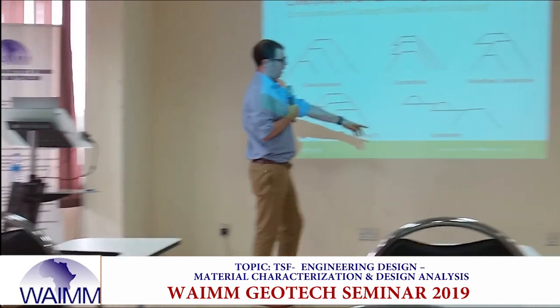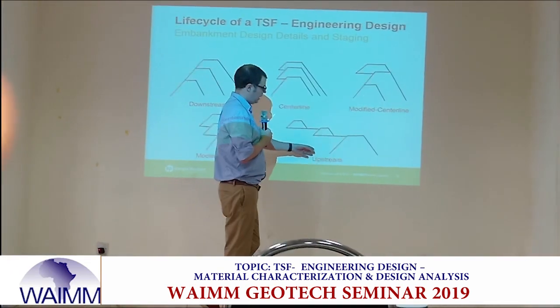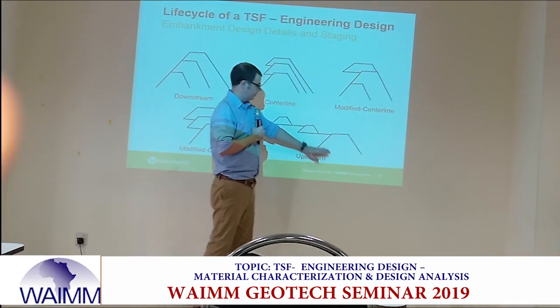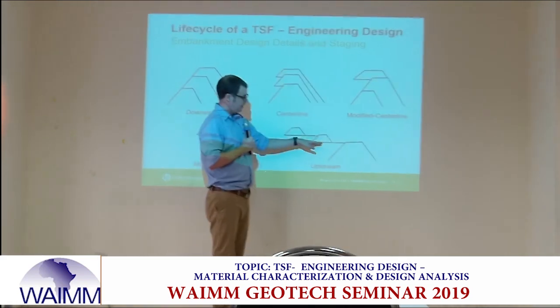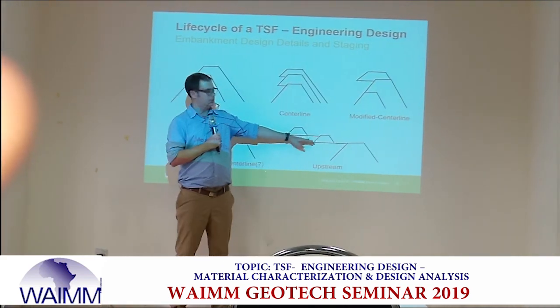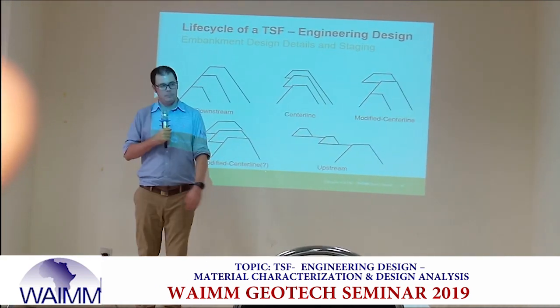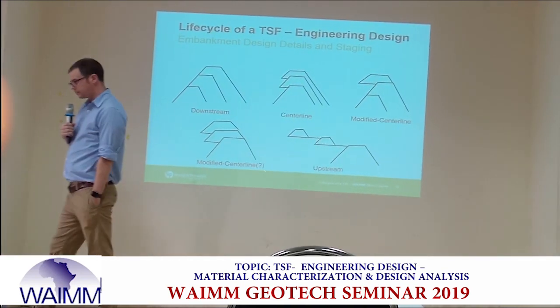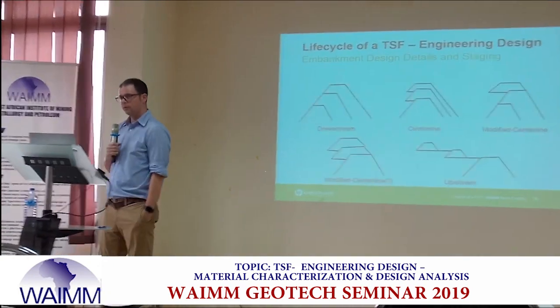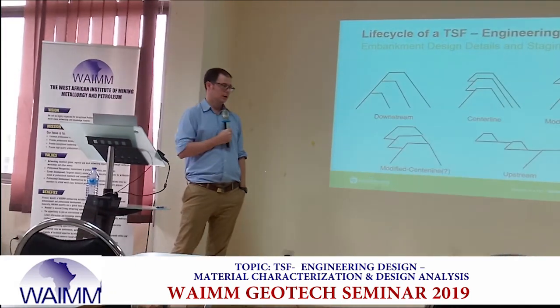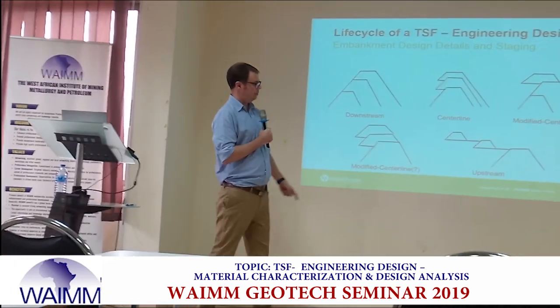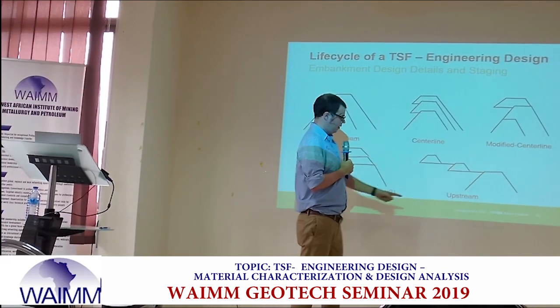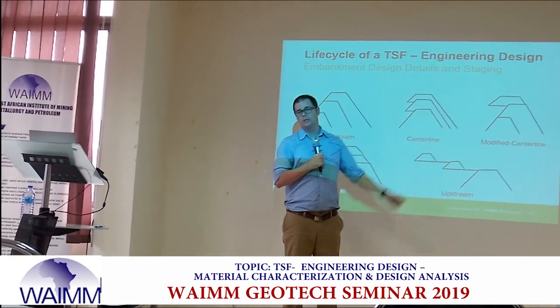Or we have a true upstream raised dam, where we have our starter facility, we fill it with tailings, and then we step way in for another berm, and we step way in. These are very, very common in southern Africa, in places with relatively dry climate and low seismicity. There are a lot of places that don't allow these at all.